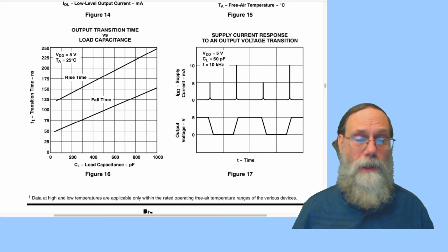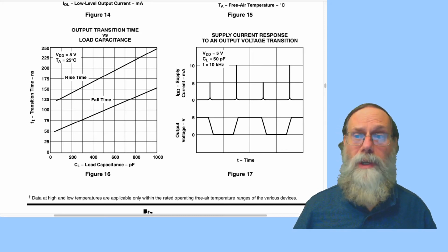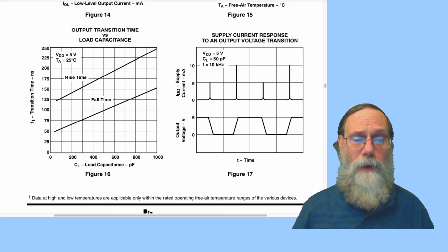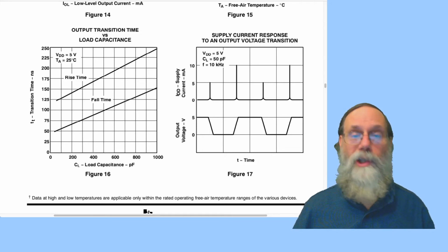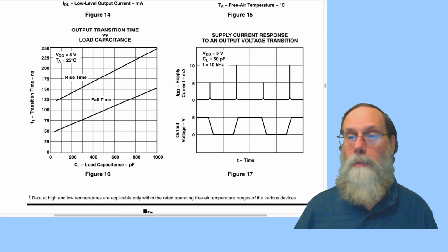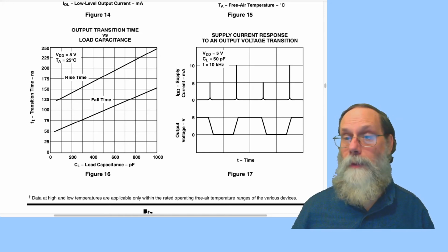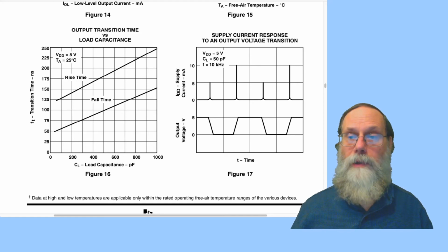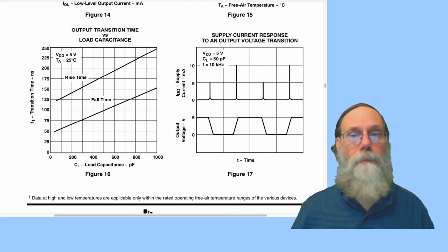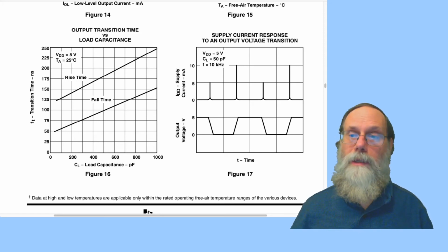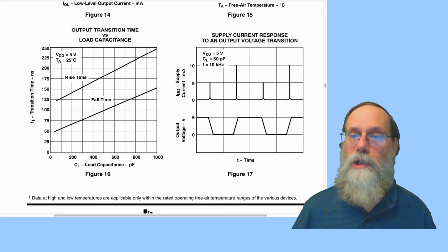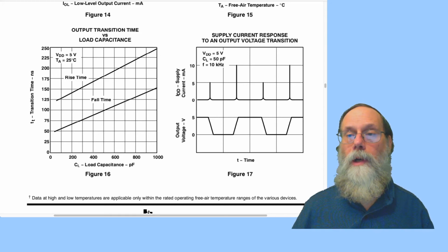But the data sheet here turns out to be pretty close to what we would have estimated from the DC values. The slope of the line here is pretty much in agreement with what we got for the measurements or data sheet values for the on resistances. And that means that any of these methods for estimating the transition times on the comparator are going to work fairly well.